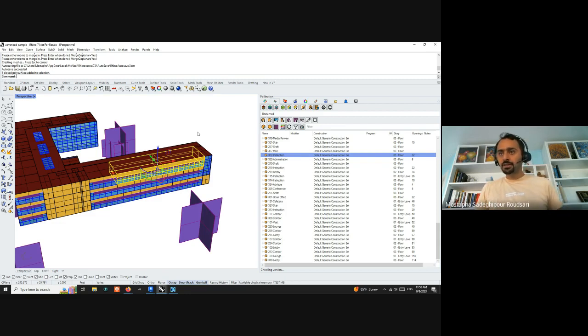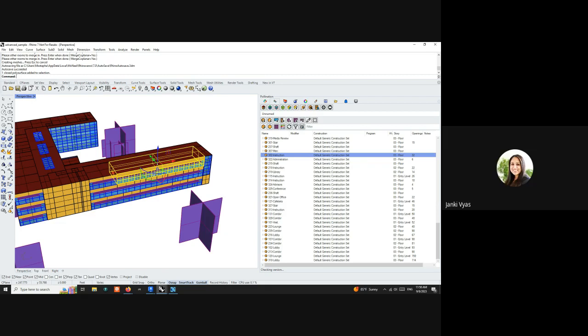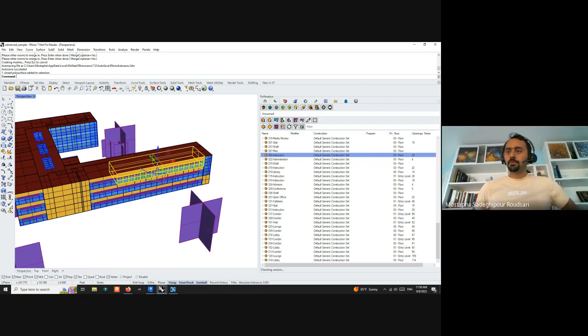Any other questions that we have here? So the question from Jackson about a previous video. I saw there was a limitation for models that were not built orthogonally, or the geometry was built with rotation. Okay, so let me be clear. The only limitation was if you have a skylight and it is rotated, that skylight will not be exported correctly.